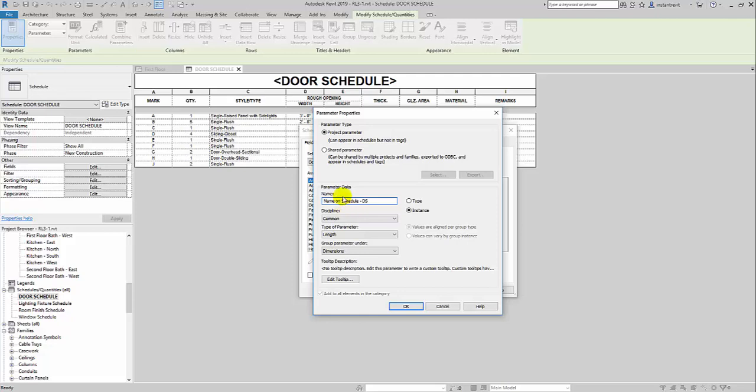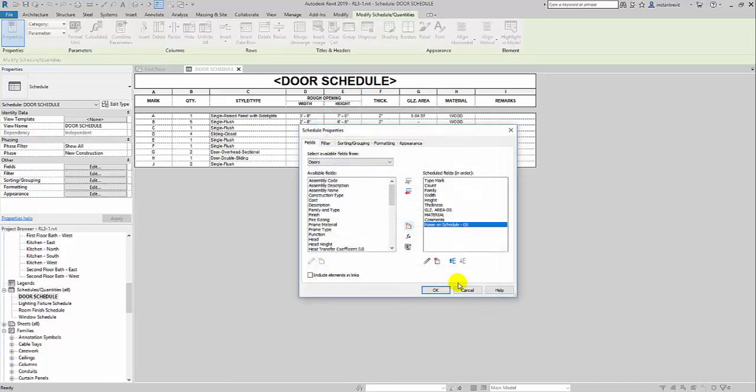And this will also be a text parameter. The reason why we're doing this is because we want to be able to show the style type in all caps, and we can't do that without renaming the family, and I didn't want to do that, so we're just going to create another field here. So I'm going to put this right after count and right before family.